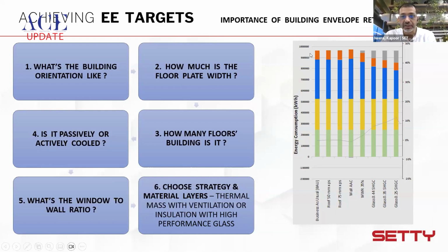What you see here on the right is a particular case where the building is thin on the floor plate, and you are making certain choices related to the envelope and how much savings it is contributing. This being a slightly tall building, on the right you have the savings as a percentage of the total energy. The gray that you are seeing at the top is essentially the savings that you're getting from the various EEMs. So the roof insulation is hardly having any impact.